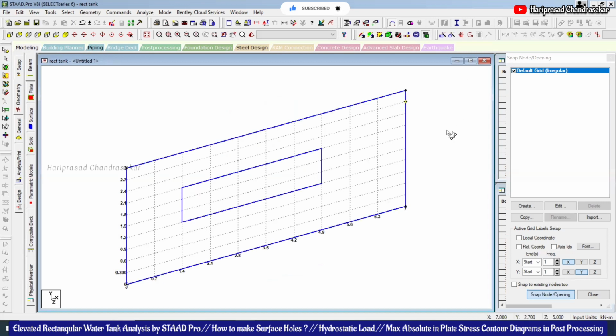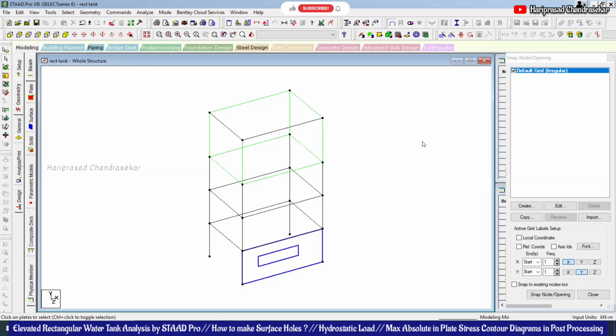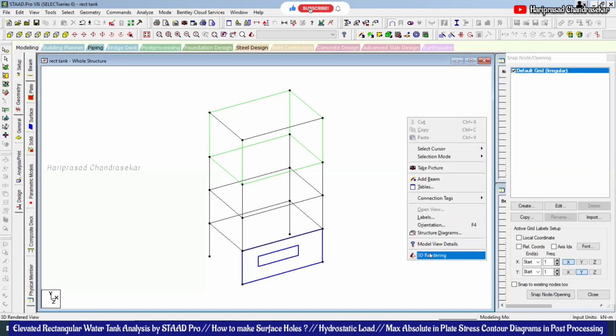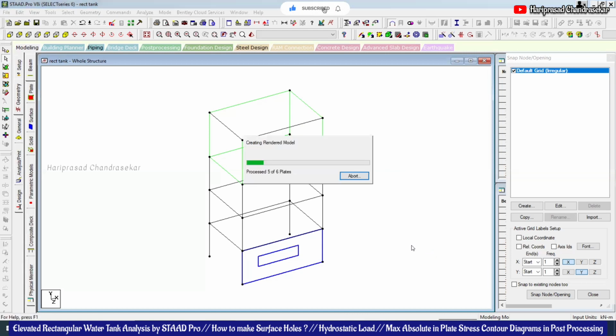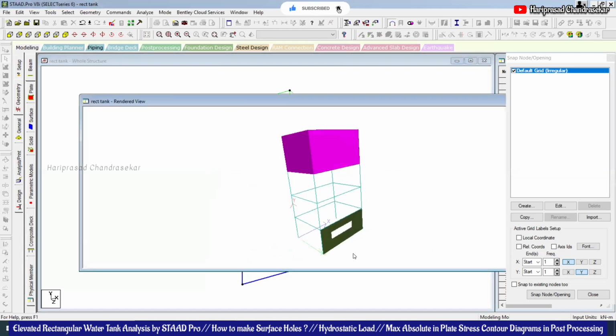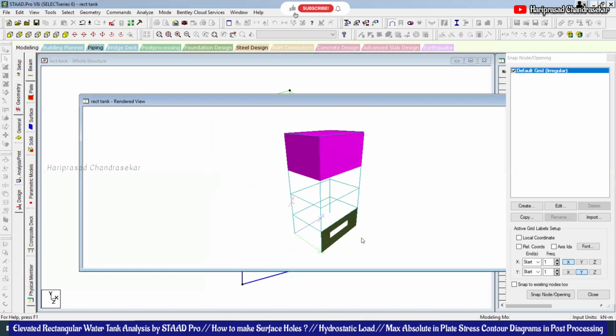Any surface or plate, whatever we take, we can add the properties as required, right? Like the thickness you are asking about, that we can provide for plates and surface. I can apply it as concrete, right? Let's apply, because when we apply loads on it, then we need to find out. See, now you can see the opening also coming. This is what you are asking, but that is not possible in plate.